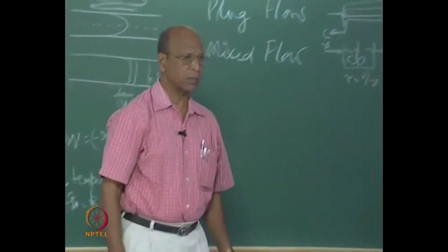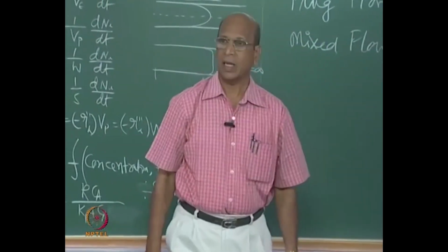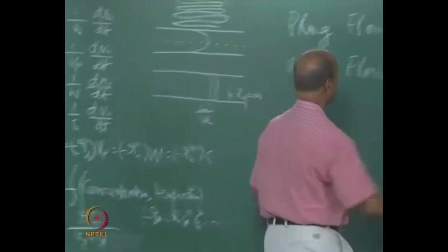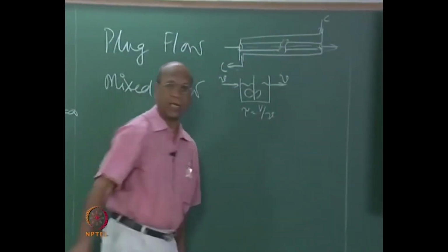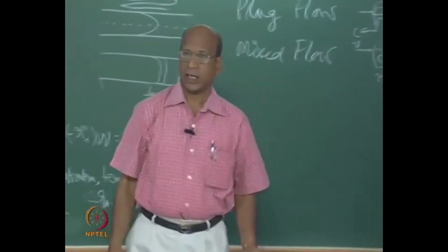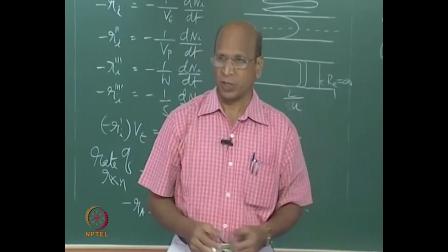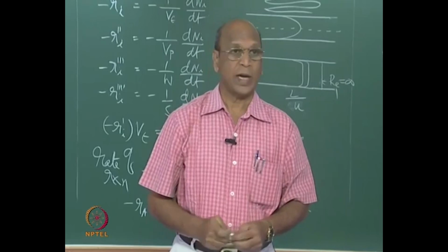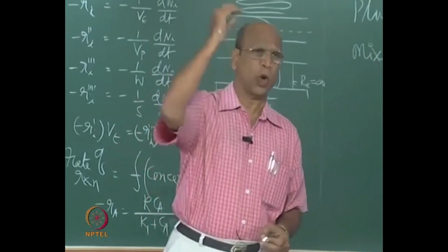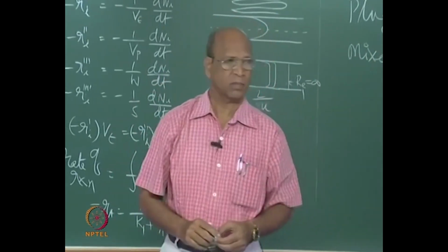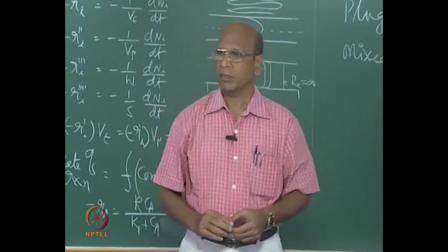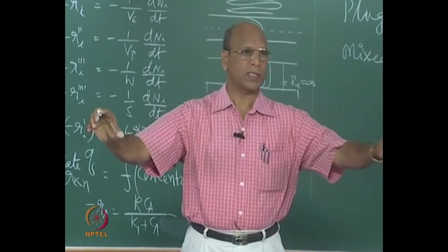Savita, you are telling something? This exchange is never perfect. You can never maintain isothermal condition in a plug flow reactor and you will have what are called hot spots. Okay, that is why plug flow reactor is a lousy reactor for heat exchange. Remember that, really lousy. You can never have uniform temperature throughout.